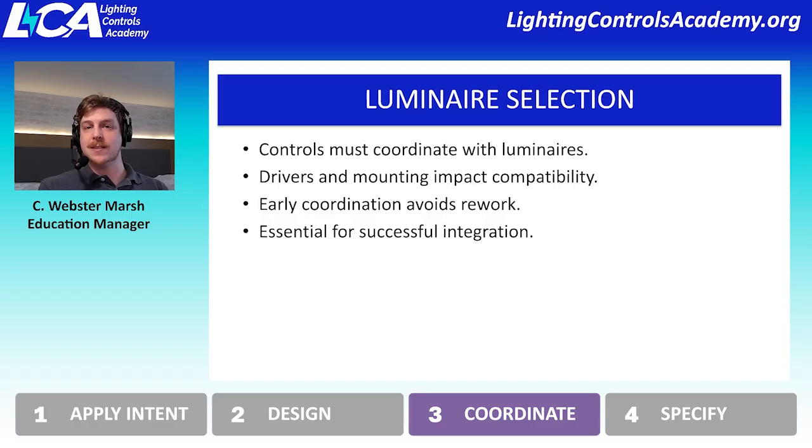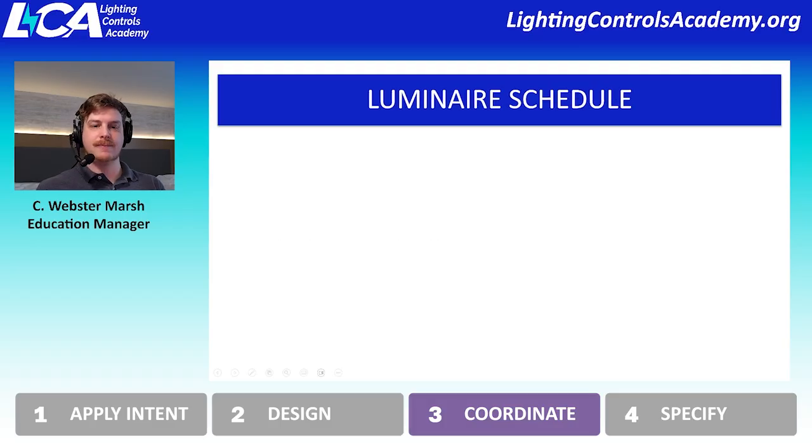We oftentimes see integration with lighting control systems at this level with DMX, so making sure that you've identified that the fixture is communicating DMX, that the controller is communicating DMX, and which version of DMX is being implemented. All of that really needs to be vetted and verified, because if it's not, then you can have some really unfortunate results that result in costly reworks or reinstallations.